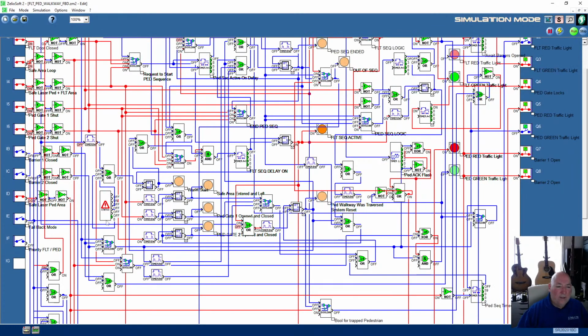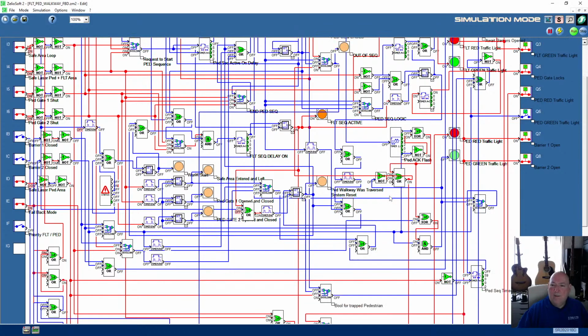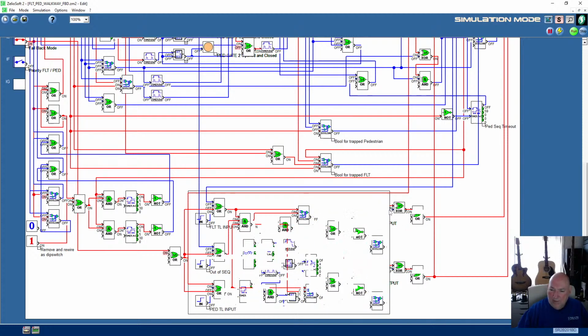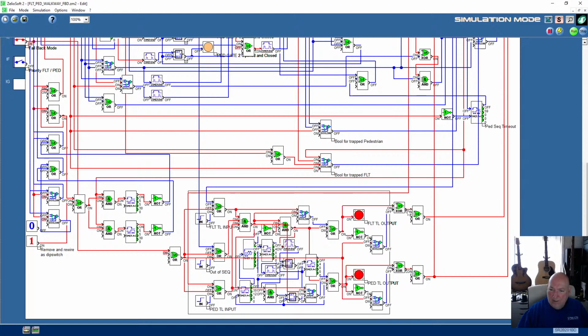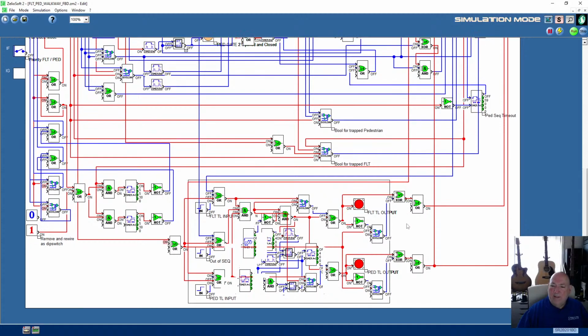Right, let's switch on, see what happens when we switch on fallback mode. Right, now it's switched on the light. Both lights are on. Okay, so that's not quite right, so I saw it wrong there. So we're switching, and it's exclusive ORing, but we've got a continuous state on the output of the OR. So that's why we see permanent.